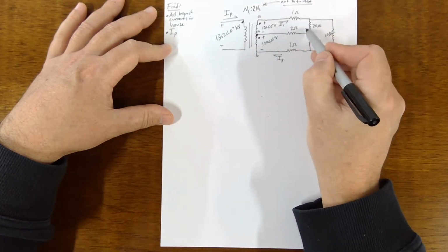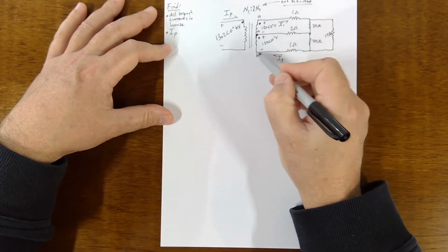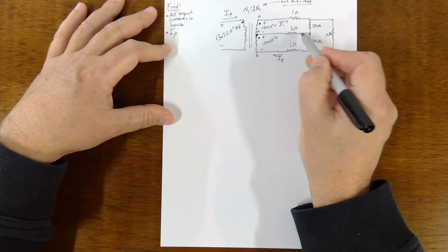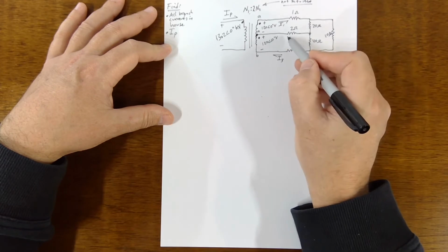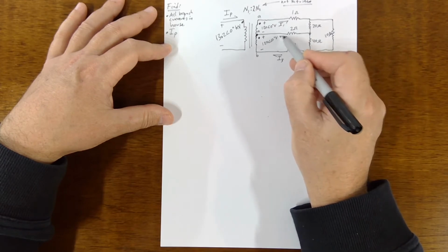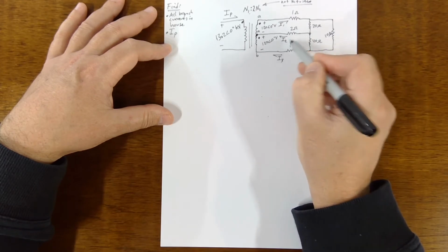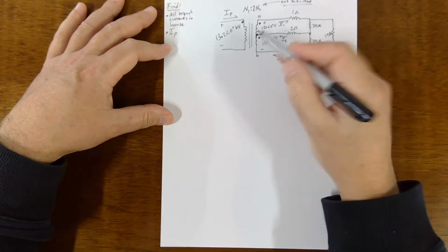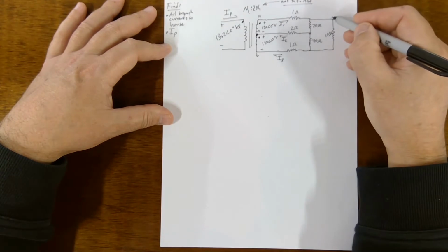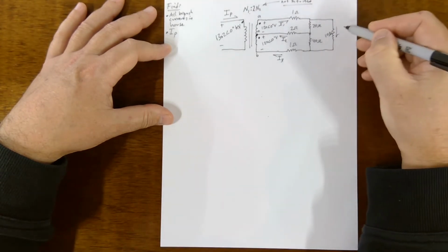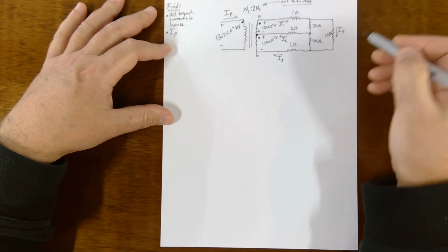It's coming out of the positive I1, and then I3 is going into the negative. There's a branch current in this line here. Hard to say which way it's going. This is more of a guess than the others. Let's guess that, so this is I2 going that way. And I4, we've got plus up here and minus down here, so the voltage is higher up on top. A good guess would be this way.